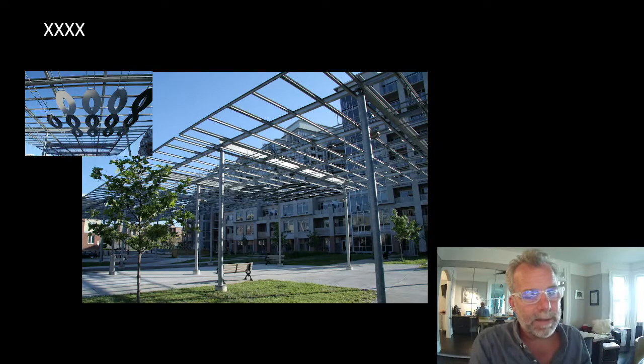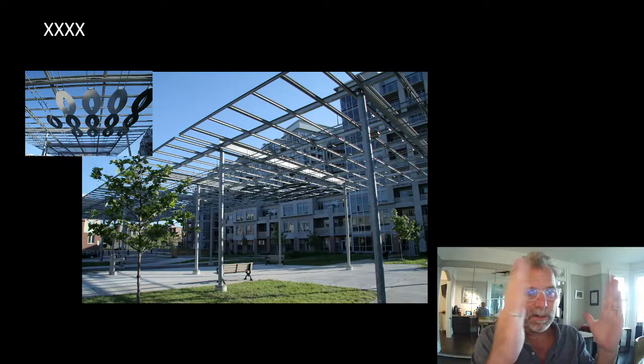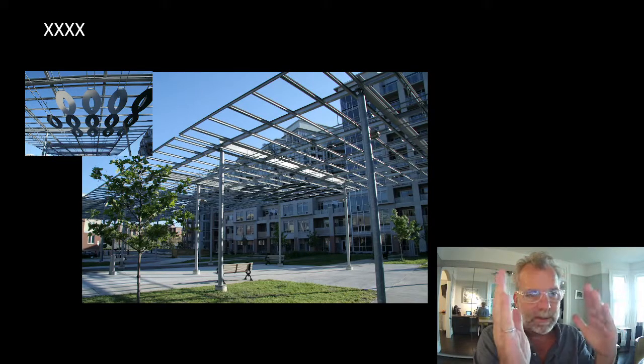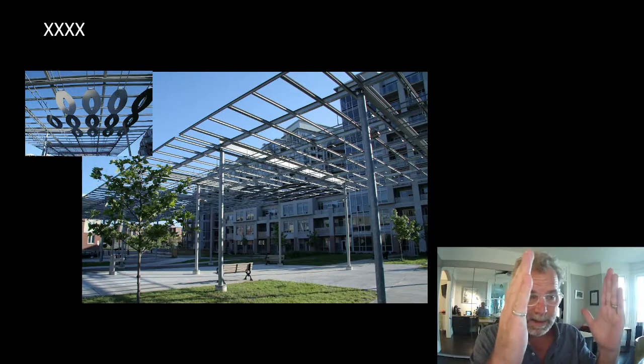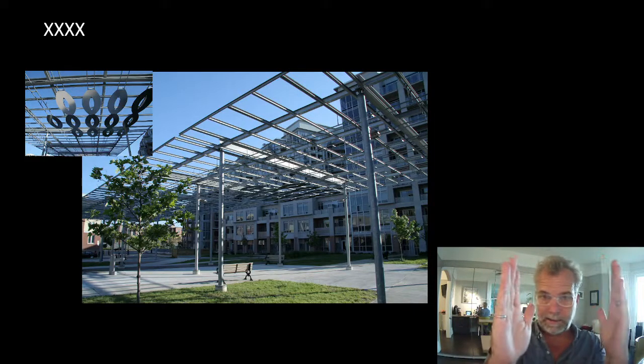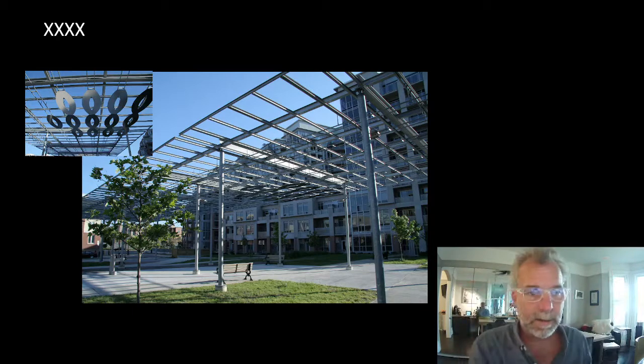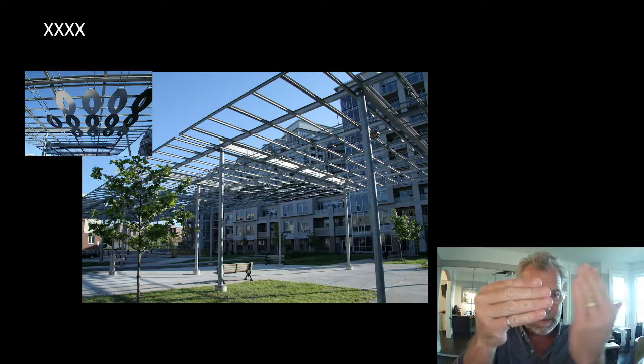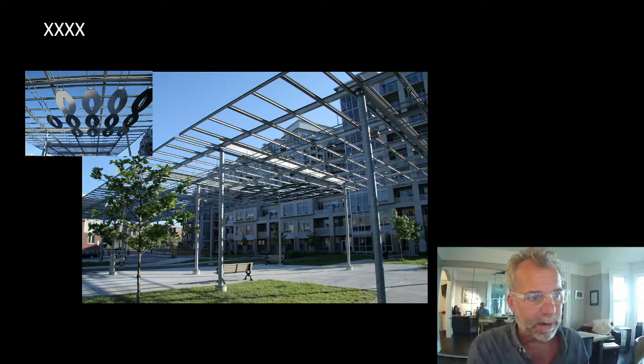That the frame typically has enough movement. The frame is connected to the structure, so the frame goes for a ride with the structure. The glazing is rigid, so it stays. So while the glazing stays, the frame is doing this, and H/500 is about making sure the glass doesn't actually slip out of the frame and break the seals. And of course, that has nothing to do with our canopy.